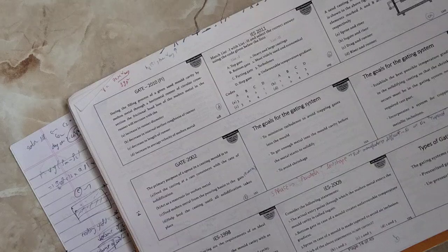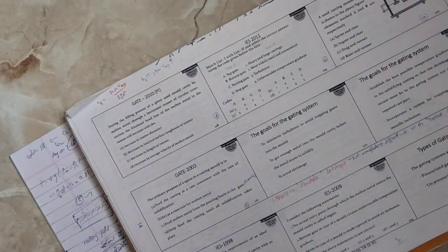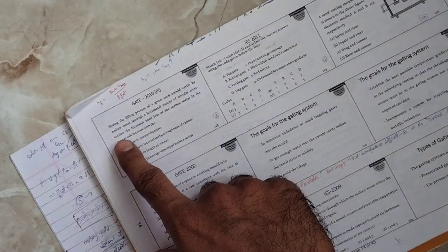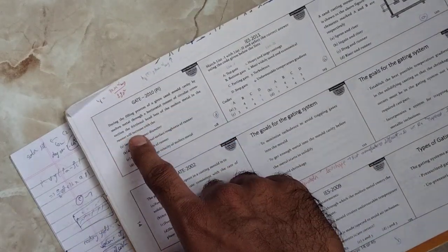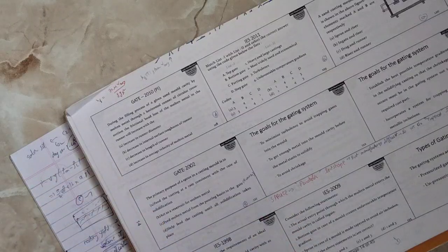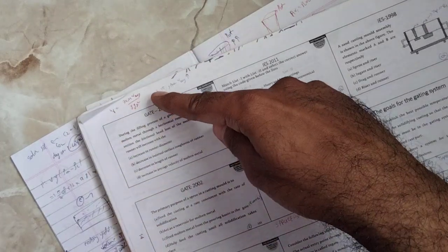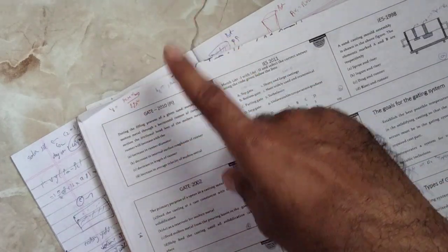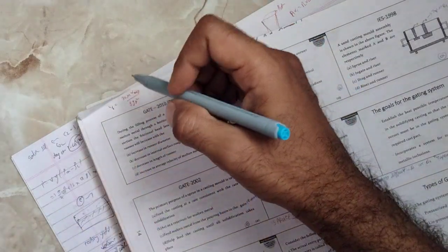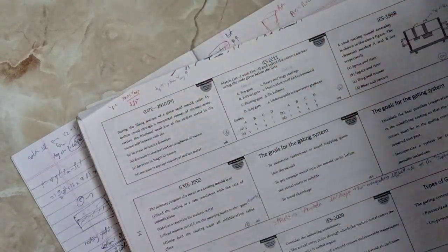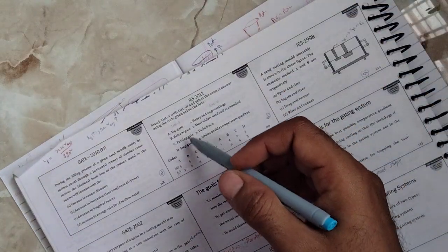So the basic thing is you can see h equals 32 mu V average divided by rho g d squared. So they are asking about the frictional head loss of the molten metal in the runner during filling through the horizontal runner cross section. So the friction will increase when the runner diameter increases? If we increase the runner diameter, the friction loss will decrease, and it decreases with decrease in length. But when we increase the average velocity, the friction will increase.